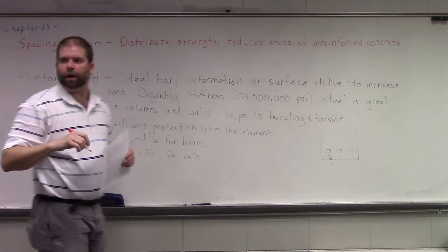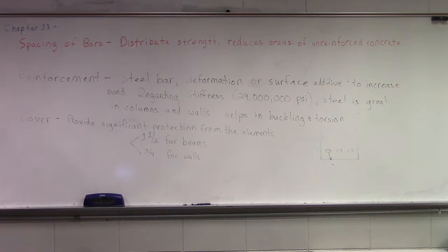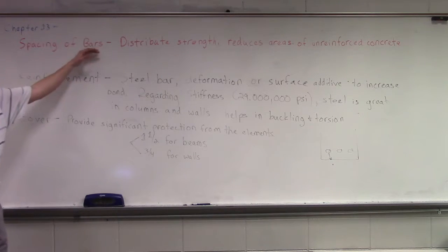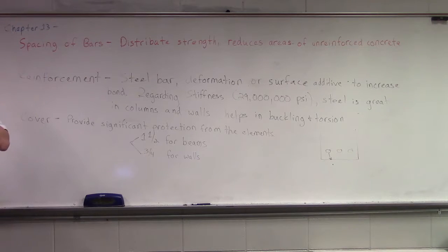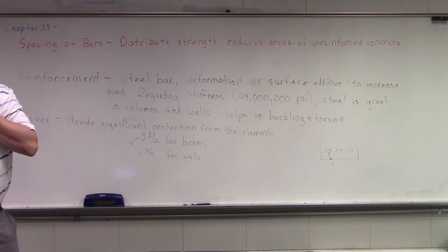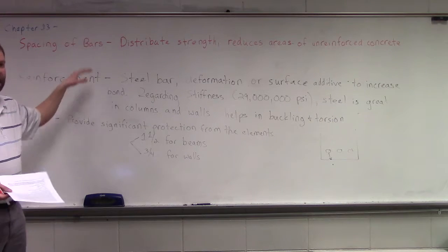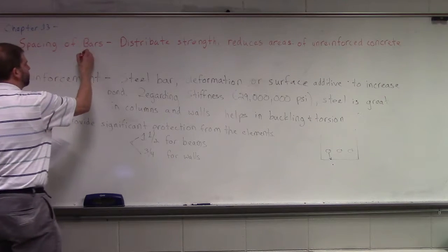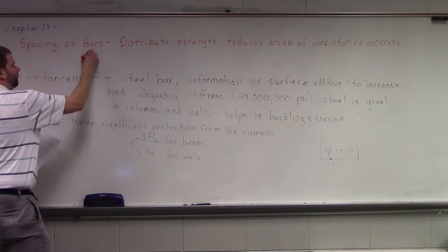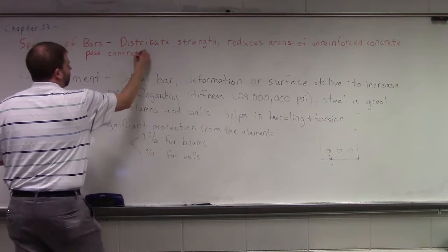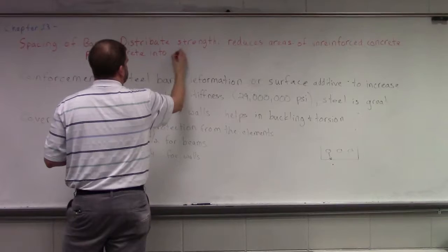And then what do we talk about? What about the concrete itself? What happens if we aren't mindful of the spacing of our bars? What could be a problem that the concrete could experience? Yeah, if we aren't able to push our aggregate through, right? And then we no longer have a concrete, we have a mortar that's pushed through, and then we have a bunch of rocks just sitting all over, right? Okay, so we want to make sure that we can pass concrete into our forms.